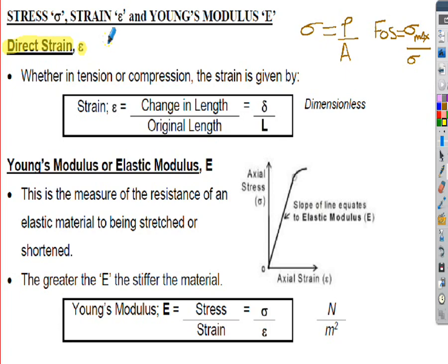And this relates to components that are in tension or compression. The direct strain is defined as this formula here, and that's the change in length, which could be an extension or a contraction, over the original length of the component. And again, I've got some Greek symbols here. Greek symbol lowercase delta, that's a very small d, curly d there, over the length of the object, which is L. So that's another formula that we're going to use.